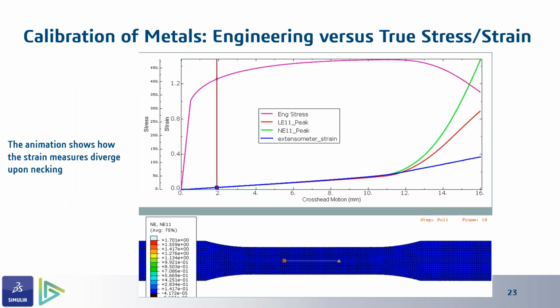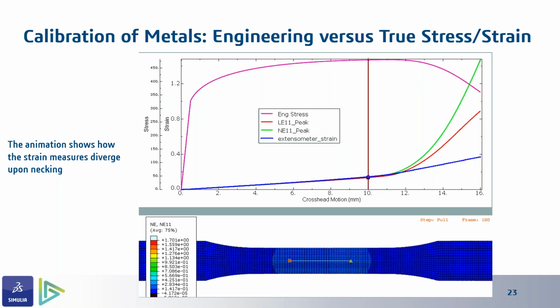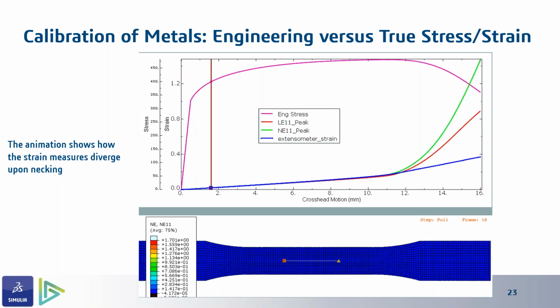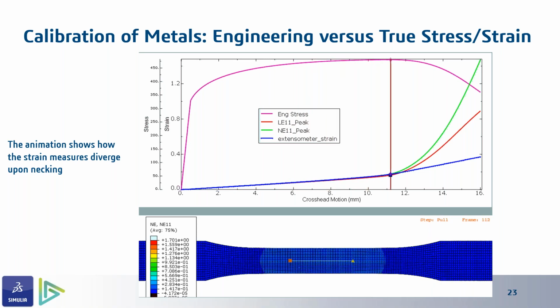So with yield data, you should always remember Abaqus wants it in the form of true stress versus logarithmic strain. So in case you have engineering stress and strains or nominal ones, Abaqus gives you the option of converting them to true strains and stresses. One thing you should remember though when you calibrate using metals, you should always consider the last point to be the ultimate stress point, or the ultimate tensile or compression point.